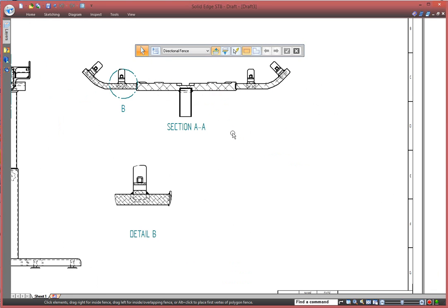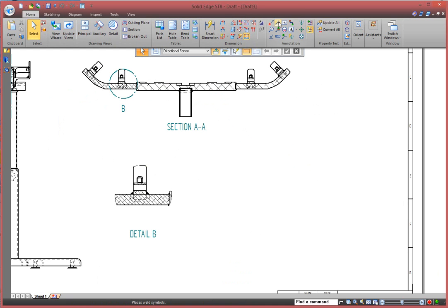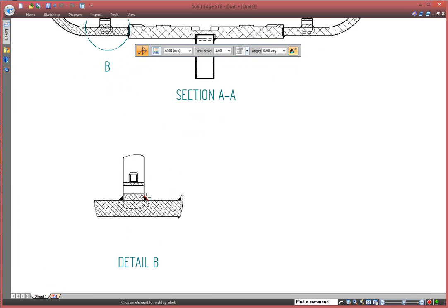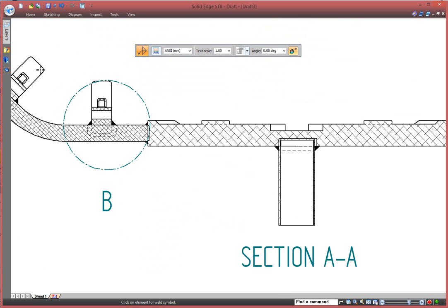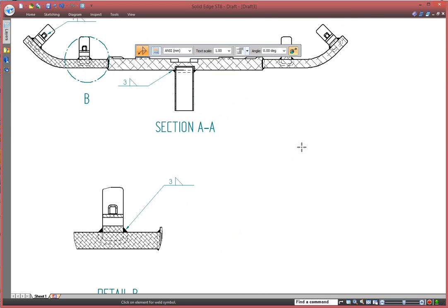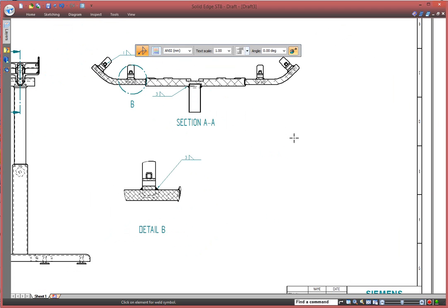As I mentioned, we have the weld nomenclature applied to the part, so to retrieve that, all we need to do is to use our annotation tools for weld symbol, and on our weld symbol command bar we've got a tighter geometry, so it will pick the detail of the weld directly from the geometry. It makes it very effective. Let's pick off this weld here. There's a little 1mm weld in there. In here I think we've got a 3mm weld, and so on. It'll pull all those, it'll extract all that information. You only have to capture the data once.